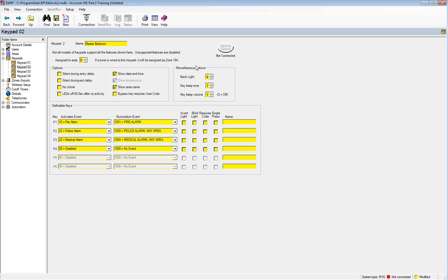With the exception of our arming station, each keypad that we offer, we've got like 5 different keypads that have this option, will have a zone and an output available. So you've got a zone input and a 12 volt 50 milliamp voltage output available off of the keypad harness. The address of the keypad is going to directly assign that zone and that output number based on that address. So we can see on the screen here we have our keypad 2, and it has zone 194 assigned to it. This also means it has output 194 assigned to it, and that output can be controlled through rules.